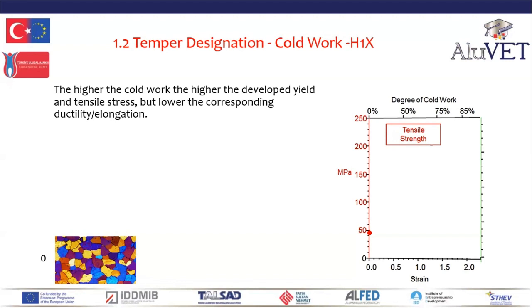Now in this slide, we've got a micrograph of a fully annealed aluminium alloy in the O condition. So it has minimal strength. And you'll notice that the annealed grains are equiaxed. And on the right-hand side of the graph, just below the number 50 is the strength indication of that alloy. So we've got an annealed alloy in the O condition.